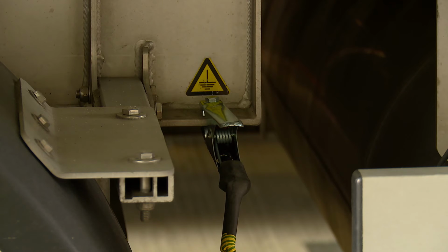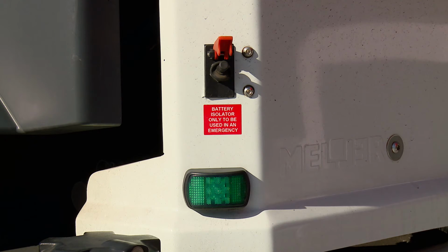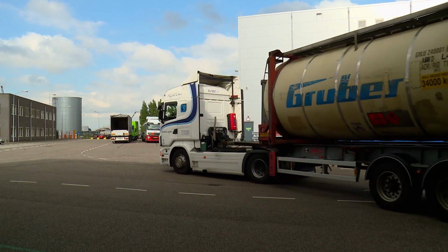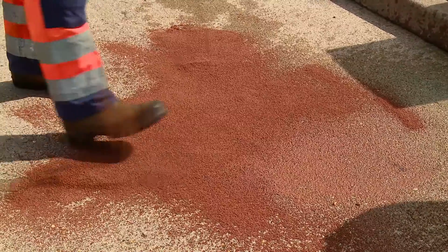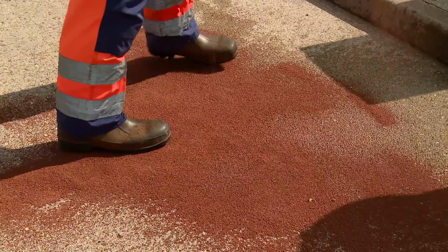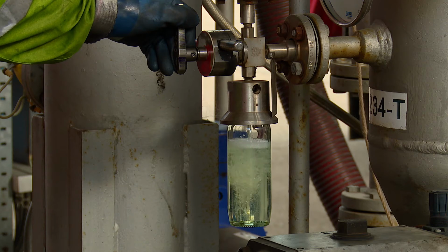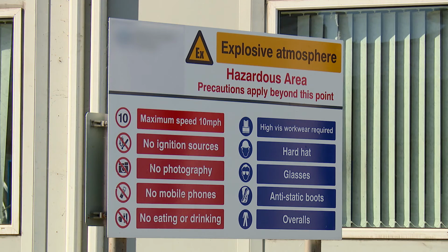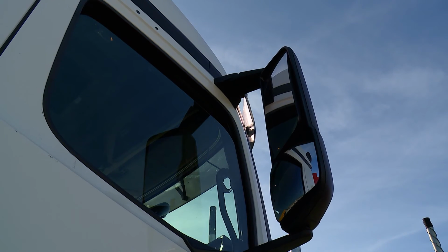In summary, make sure the vehicle is earthed and electrically isolated prior to any other operation. Make sure that the site and vehicle emergency procedures are understood. Ensure all connections are removed prior to moving the vehicle when the transfer is completed. Report and clear up all spillages immediately, and always comply with the site rules. If possible, do not take samples from the top of the vehicle. Ensure there are no sources of ignition and never smoke on site.